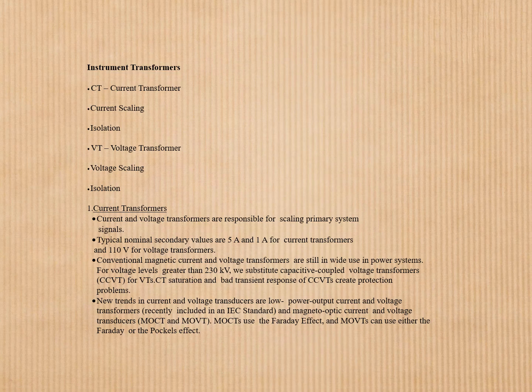Conventional magnetic current and voltage transformers are still in wide use in power systems. For voltage levels greater than 230 kV, we substitute capacitive coupled voltage transformers, CCVTs, for VTs. CT saturation and the bad transient response of CCVTs create potential problems.